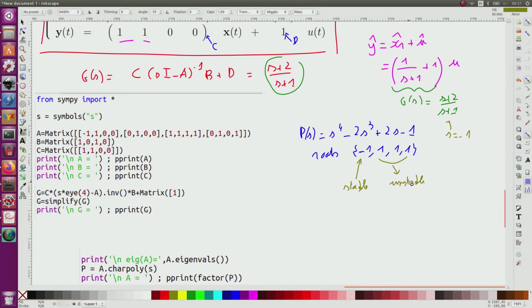And in practice, even if the input-output behavior is represented totally by this, we have to recall that the linear system is an approximation of the real nonlinear system, and the approximation has been done by linearization. So if one of the state variable is unstable, of course the approximation will not be correct. This is why this kind of simplification by unstable pole has to be avoided.